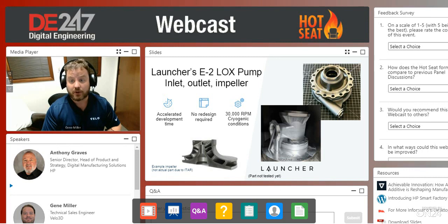And there's another webinar on this. They tested the pump, and right out of the gate, they had just huge success, which is very difficult and doesn't happen all the time in the world of aerospace or space engineering. The outlet is Inconel, the inlet is aluminum F357, and the impeller was out of Inconel 718 as well.